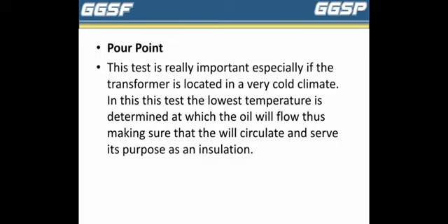Pour point. This test is really important, especially if the transformer is located in a very cool climate. In this test, the lowest temperature is determined at which the oil will flow. This makes sure that they will circulate and serve properly as insulation.